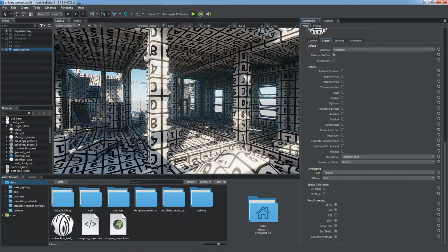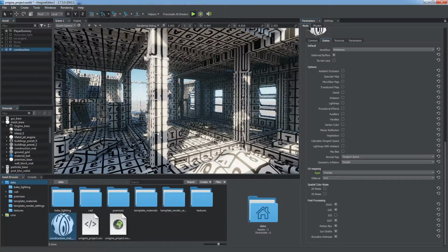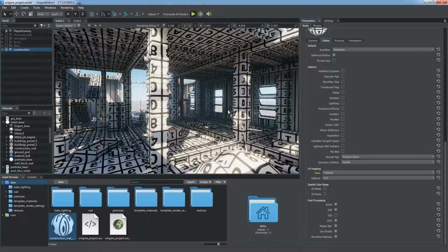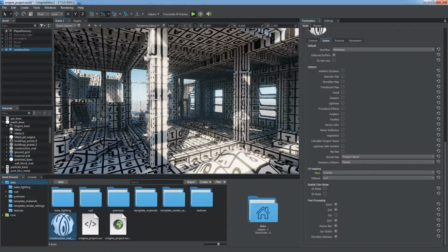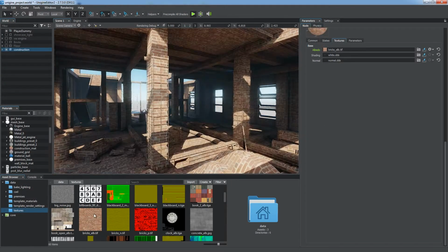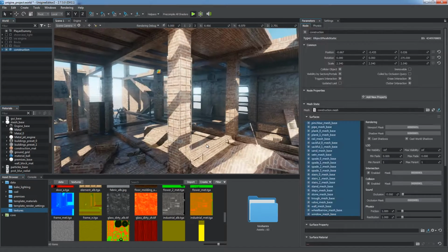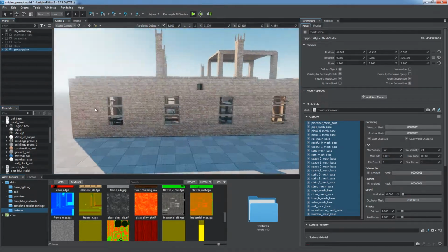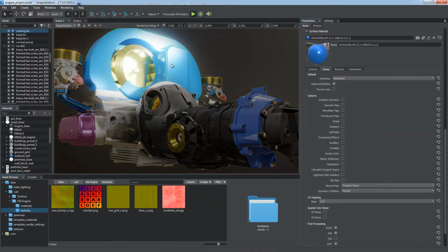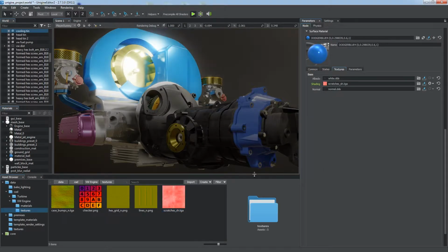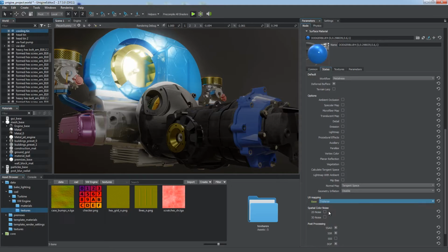There is no visible change so far, but if you apply the overlapping material to vertically oriented objects, you will notice texture stretching. After selecting the appropriate mapping type, it is easy to assign textures, and they will be mapped correctly. So if you have a problem of inappropriate mapping when applying a texture to a model, simply switch to the Triplanar or overlap mapping mode.